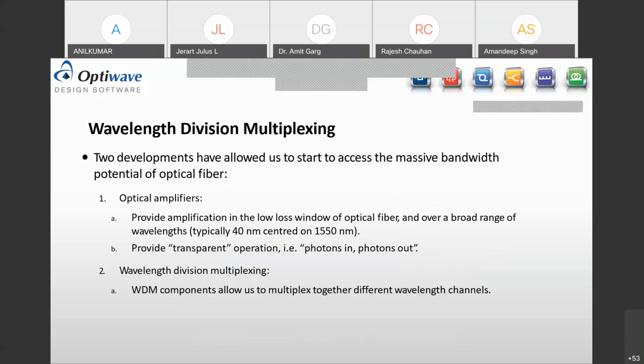Now in this WDM, what actually depends? For example, when the transmission media passes through carrying a signal, it also requires some amplification. So here we can use amplifiers, for example, erbium doped amplifiers or optical fiber amplifiers, those which can give us a gain of at least 20 dB, so that we can take the signal to a further level at a transmission point.